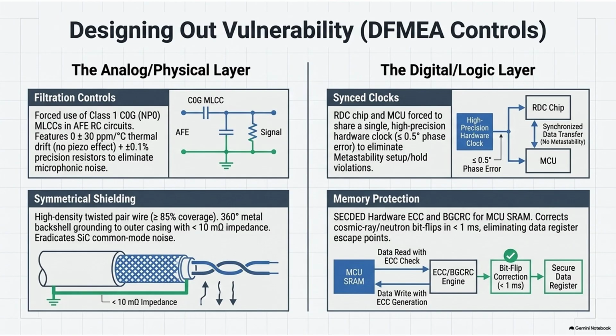It's so smart. After the robotic arm injects the grease, the connector moves under the AOI camera, which blasts the pins with high-intensity ultraviolet light. It's like forensic science on the assembly line. It really is. The camera's image recognition software must visually confirm a 100% perfect glowing pattern of grease on every single pin, while also verifying there is no spillage that could bridge 2 pins and cause a short circuit.